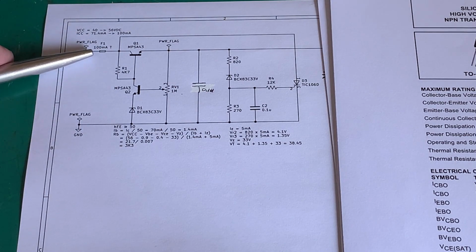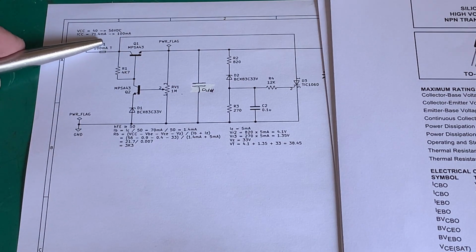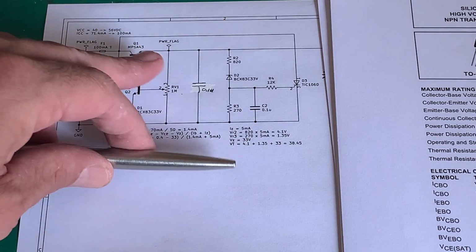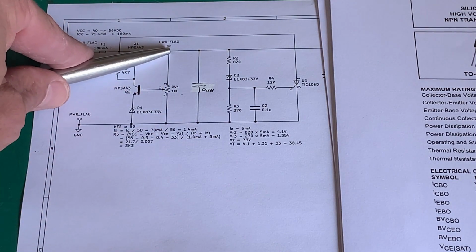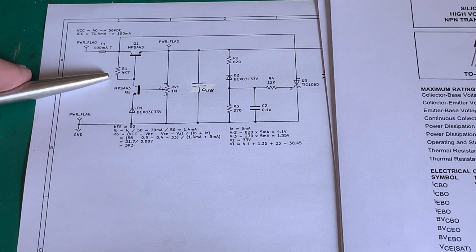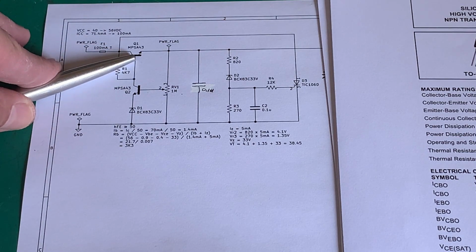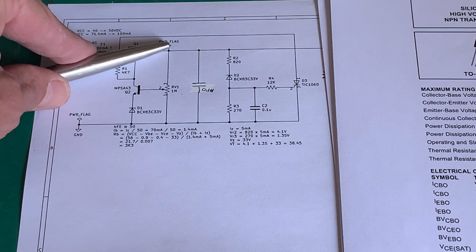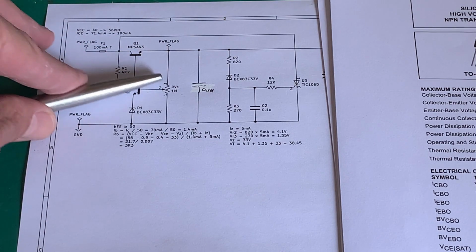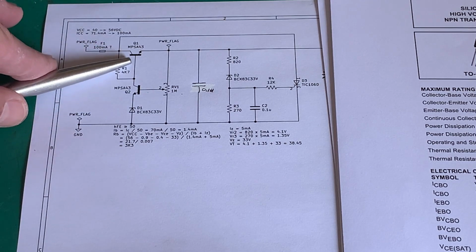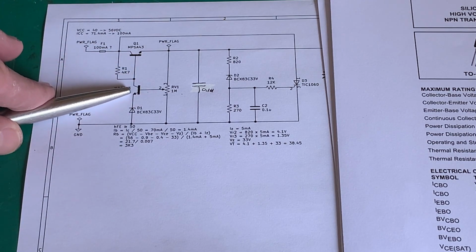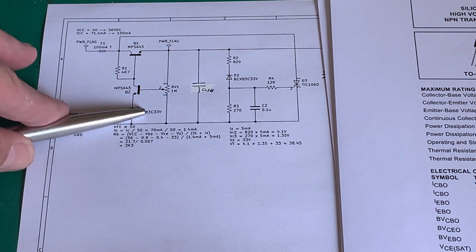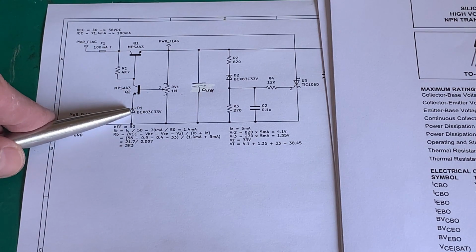So what we know is when we switch the power on, that transistor will be off because there will be zero output. We will turn that transistor on, the voltage will rise, and as the voltage rises, we'll give more feedback into the base here, thereby drawing current through that Zener diode, and that Zener diode will give us a voltage reference.